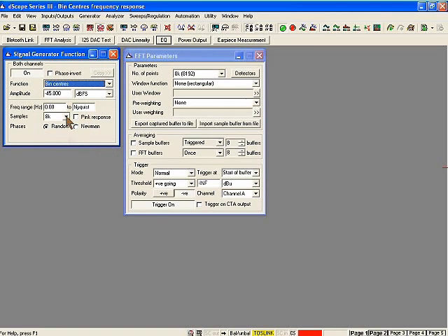And what we're actually doing here is populating every single bin frequency in our FFT that we'll use for analysis with a tone component. So in other words, there are 8,192 tone components within this multitone, of which half will occur in the real frequency axis, in other words from DC to the Nyquist limit. So this is a really densely packed multitone. There will be over 4,000 tones in the range over which we will be seeing our analysis.